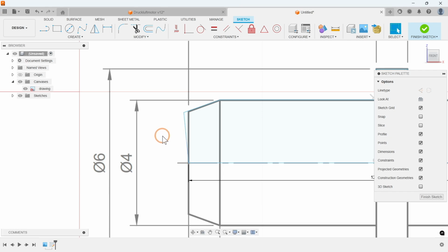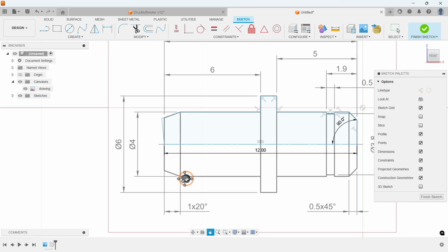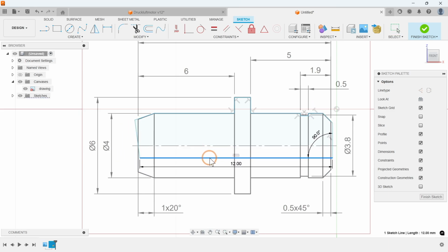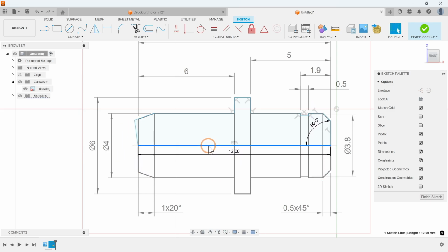Dependencies are useful because they automatically establish measurements and alignments based on your conditions. That means you don't have to manually measure the length and angle of each line, but can control many things through dependencies. After the contour is drawn, the lines are still blue, which means the sketch is not fully defined. You can test this by grabbing a line with a left click and moving it. To avoid unintentional changes, we should fully define the sketch.